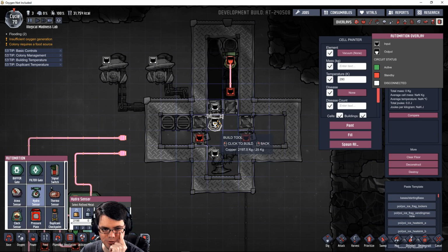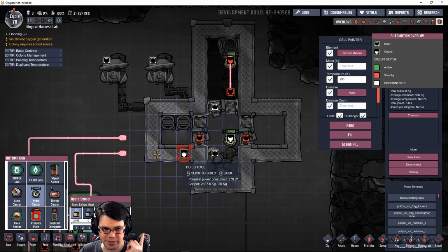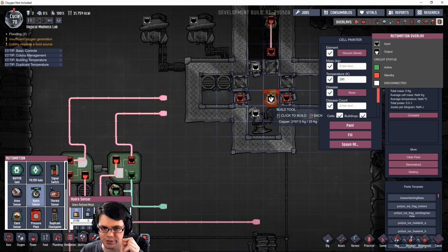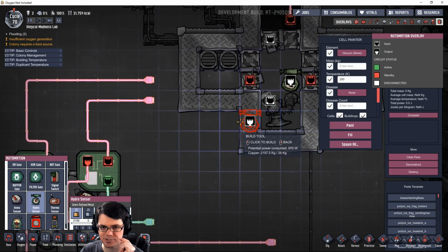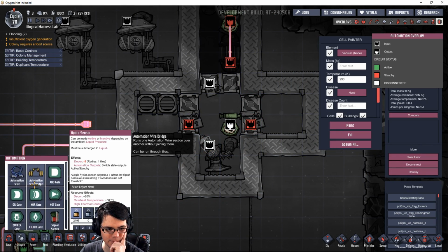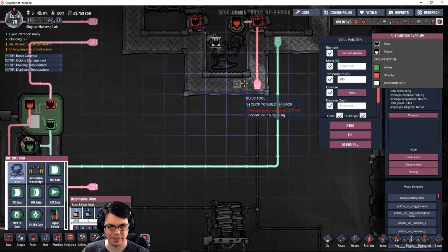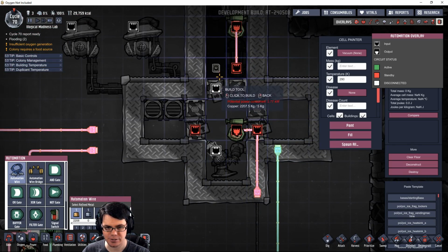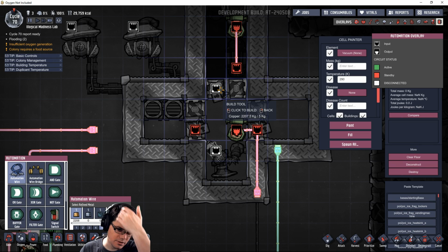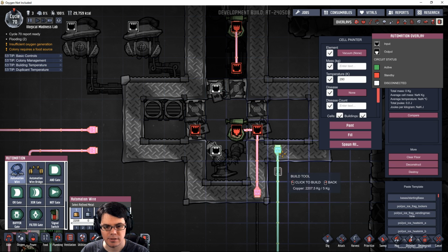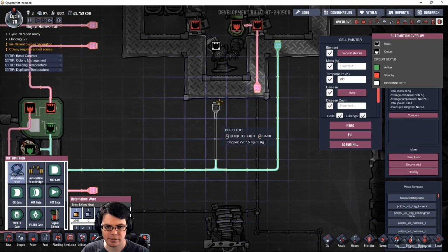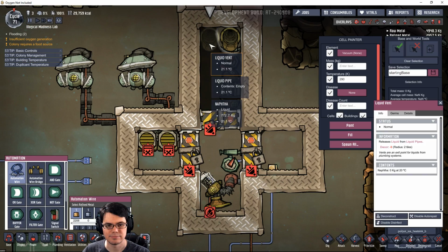Okay, I'm going to use a hydro switch that lets me know that I've built up enough liquid to trip this sensor. And that'll be the signal I use in order to turn on this pump. It'll also be the same signal I use to open that door. Let's see if I can figure this one out. Okay, so if this is off, then I want that door. No, I want this pump to run. That's what I want.